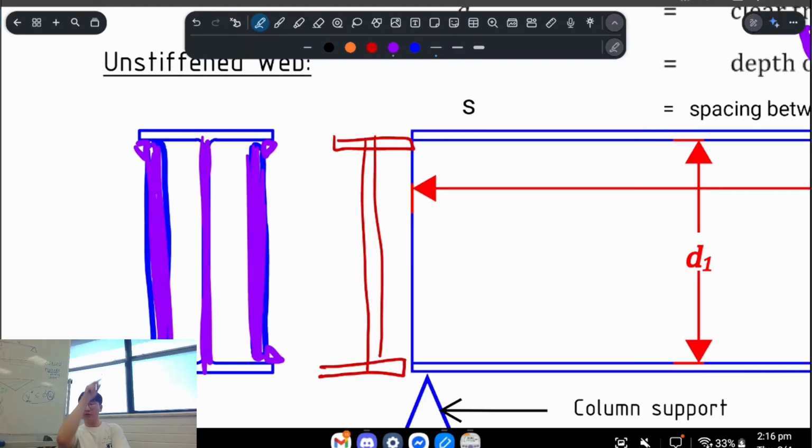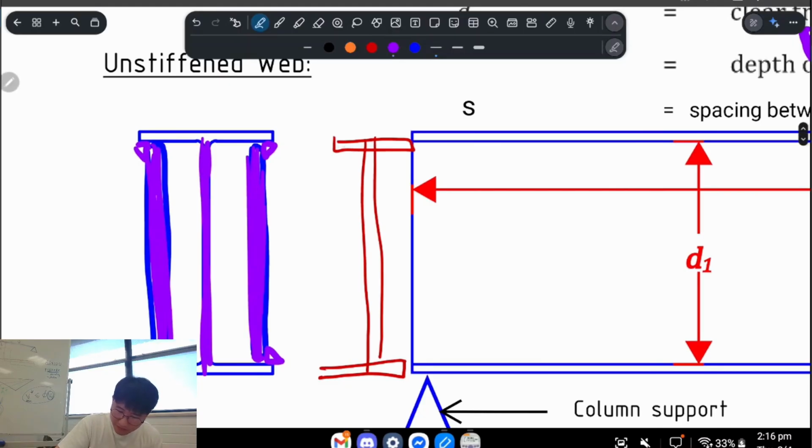We're talking about vertical shear. So how shear forces want to flow is it goes vertically through your I-beam from outside in, basically, right? And the majority of your shear force will be taken by your web, okay? Just trust me for now. It makes no sense until you see the calculations.